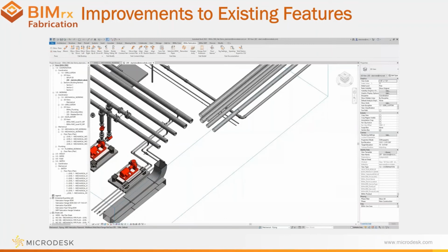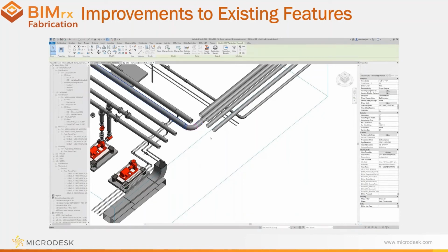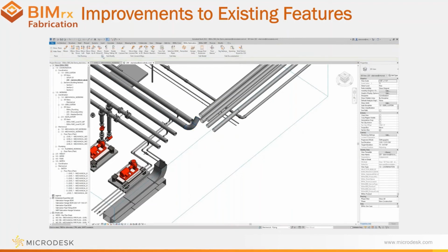So let's take a look. Now, starting out, I'm going to use the elbow command to show the standard stub that we get. You'll also see I'm going to be able to use the new rotate fitting command to just rotate that entire stub up at 45 degrees right off the bat. Now I'm going to go ahead and jump up and take a look at the MEP settings.